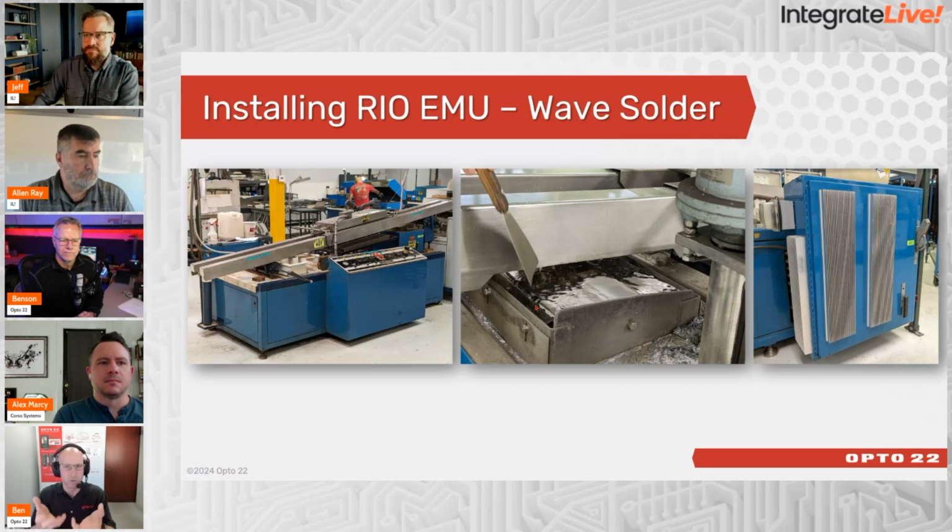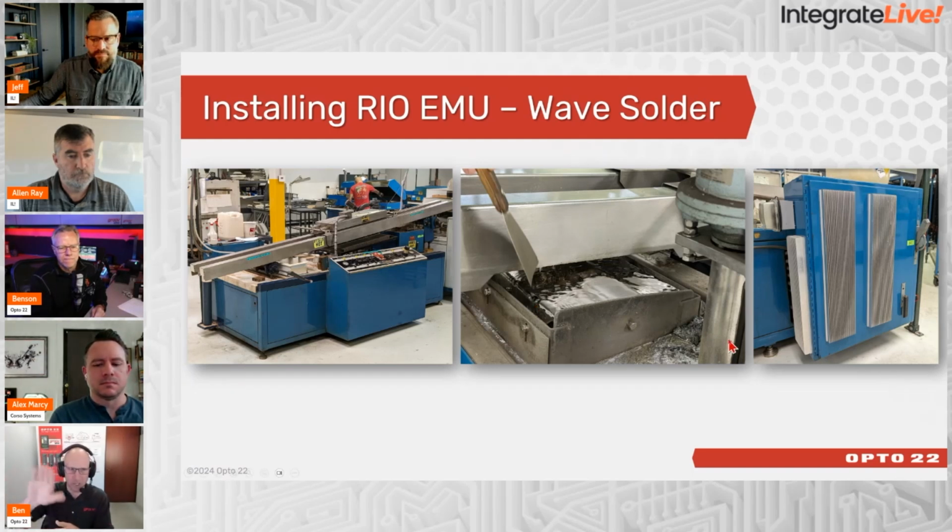Once it gets to the correct temperature for the particular chemistry of the solder, it'll hold that temperature. Then it's got various thermocouples, which takes us to our picture on the far right. We've got the blue electrical cabinet with 3 big heat sinks. They're not quite variable frequency heater elements. They're like a TPO, bang on, bang off, temperature controlled TPO, PWM. Each heat sink is for one of the 3 phases, modulating the power going into the resistive heating elements underneath the core.